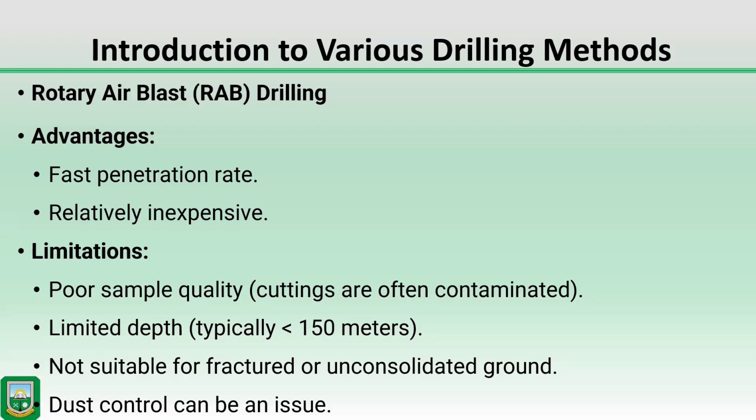It's not suitable for fractured or unconsolidated ground. When you are dealing with ground that has a lot of fractures, in such an area you cannot have a good drilling. And why is that so? Because we are using compressed air to blow the cuttings to the surface, so we need the walls of the drill hole to be solid. We don't want any fractures within the drill hole. Because when you are blowing the cuttings to the surface with compressed air, and there are fractures within the drill hole,